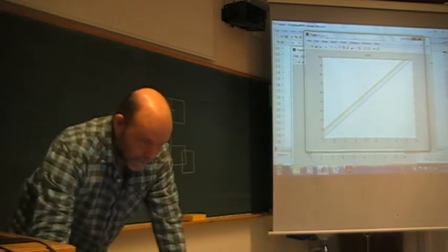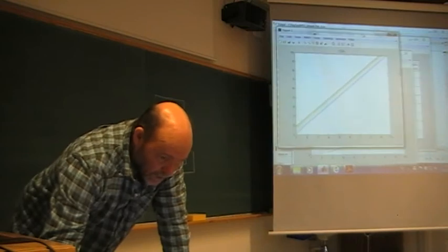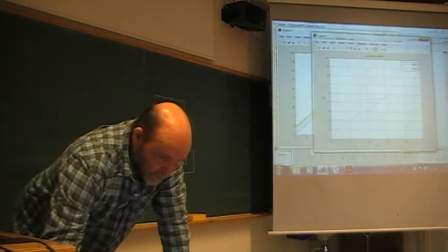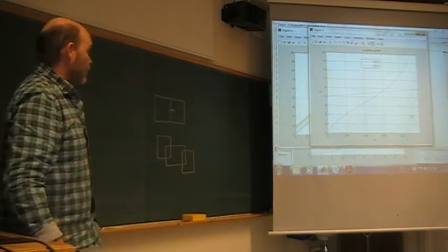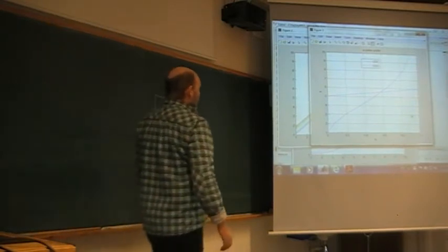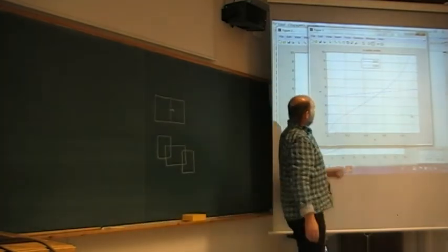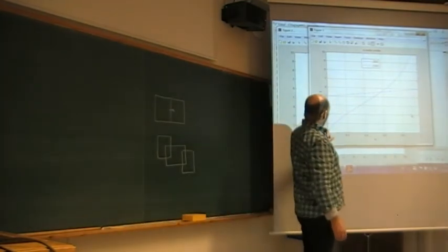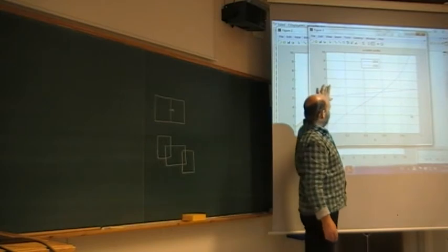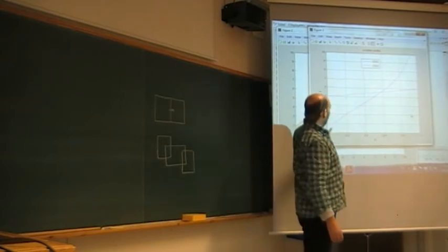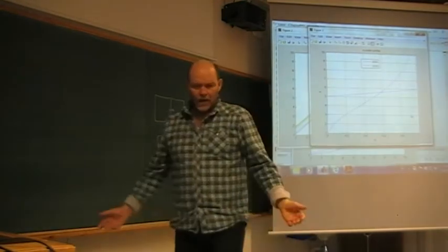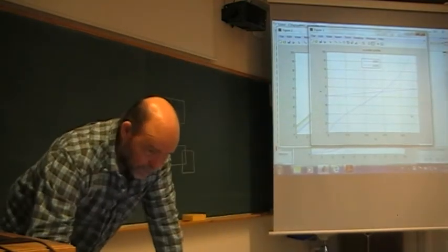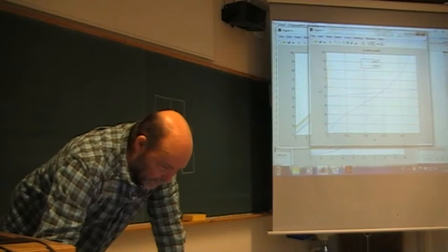I'll come back to that, how this is done. For the smearing out effect, it's just the center profile here. So the central difference scheme actually makes the jump over one cell, as you should, but the upwind scheme smears it out. And here you can push on so many cells as you like. It really doesn't help.